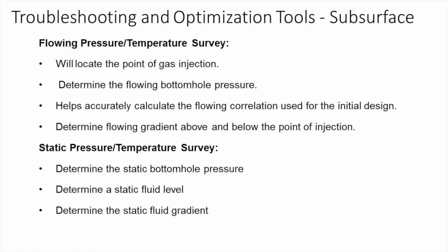Of course, the best one is a pressure temperature survey. Pressure temperature survey gives you real-time information downhole of how the system's operating. And you can take that information to improve a gas lift design, adjust injection rates, adjust surface facilities to maximize that flowing bottom hole pressure.